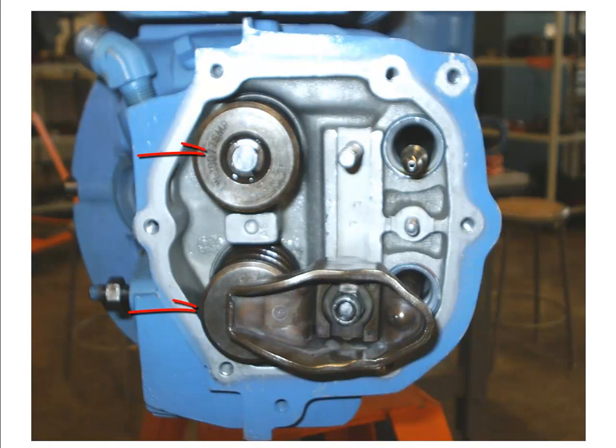We've got two valves. One, again, the exhaust valve here has the rocker arm installed on it, and the rocker arm is what opens and shuts the valve. So you can see some really big springs. Those hold the valve shut. And when the engine turns, it turns a camshaft. The camshaft has lobes on it that lift these push rods that you see poking out here of these smaller holes. And that rocks the rocker arm like a teeter-totter and presses down and opens the valve down inside the combustion chamber.